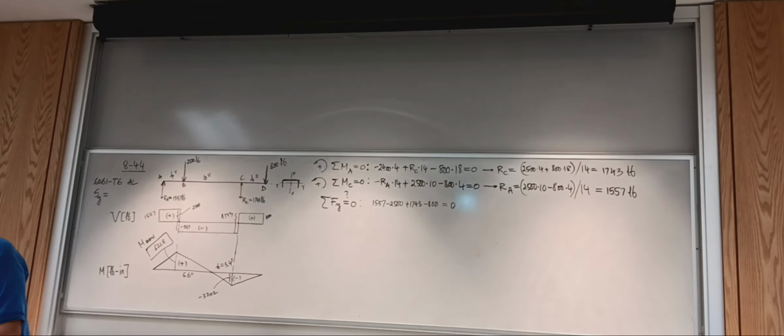On page 790, a design factor of 4 is associated with repeated loading, and for bending stresses, actually no, it's 8. Repeated loading for bending stresses, its design factor is 8. So an overly conservative static loading, we may say. All right, so N is 4.